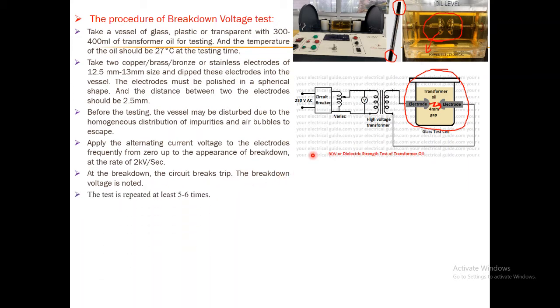Generally, when you are performing the breakdown voltage test on a liquid dielectric material, the first magnitude one has to avoid, because the first spark is created to produce a perfect dry condition between these two spheres. The transformer oil is hygroscopic in nature, so when you are pouring the liquid, it has a tendency to absorb moisture.